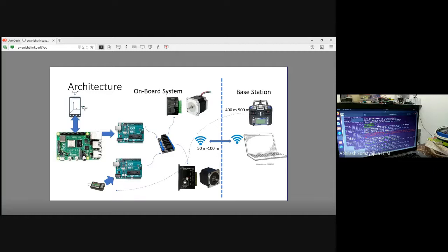It's a 3-phase BLDC motor. This drive understands the low and high level logic. Accordingly, it converts that command to the BLDC motor on a 3-phase wire. And there will be a Hall sensor in the motor which gives the feedback, and then the drive understands when to shift the phase of the motor. So this is how it communicates.